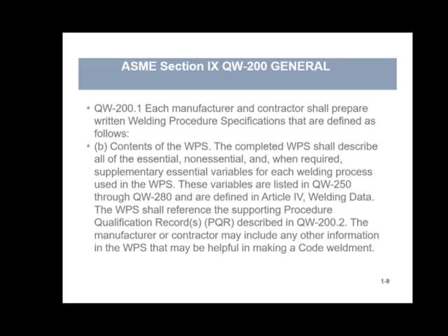You want to use the word none for essential variables that you're not going to use. They're still applicable, but you're just not using them. And you are telling the welder it's important, but this is how we're approaching it. It's prohibited, none, don't do this, do this. You're giving him some direction.